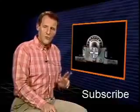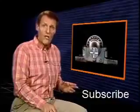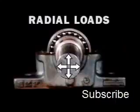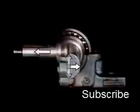We're going to discuss the two types of loads that bearings can be subjected to: radial loads and thrust loads. Radial loads are forces that act along a radius of a bearing or shaft. This rolling element bearing is designed to resist a radial load. Thrust loads, or axial loads, are back and forth forces exerted on a bearing or shaft in a direction parallel to the axis of the shaft.